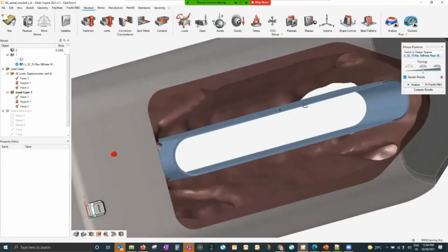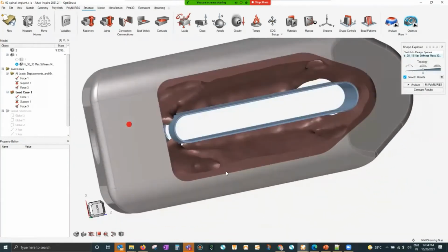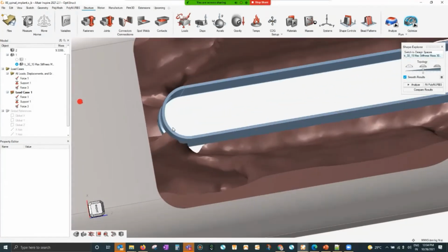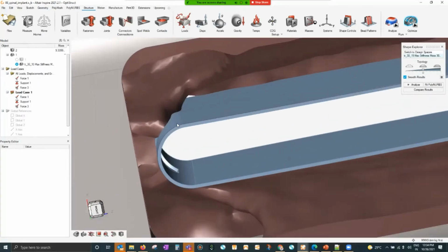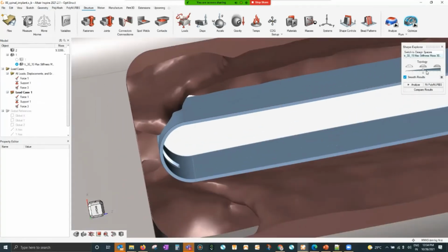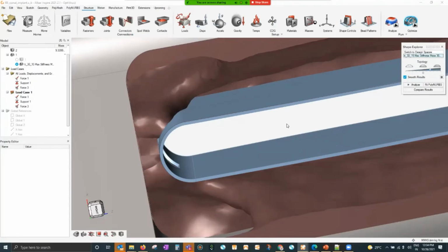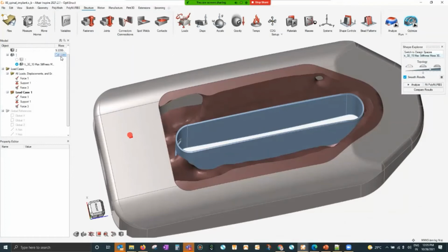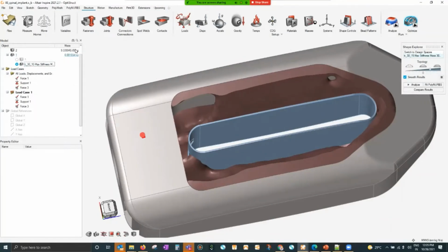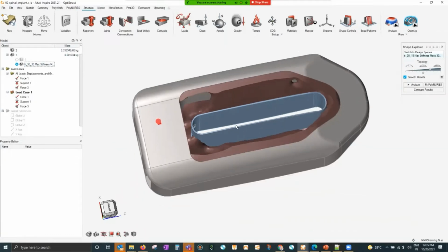So that means that 30% may be giving you a shape, but all the areas are not well connected, or if it is connected, it is very narrowly connected. So that's why I'm just sliding it two steps up so that I get some more material. Since it has optimized a lot, maybe instead of 30%, it is making 35% or something like that.